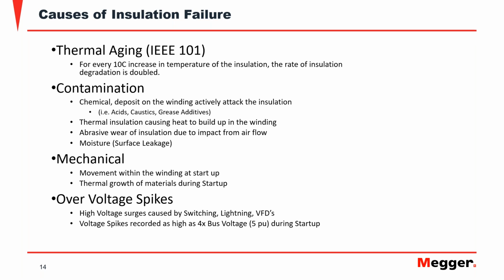If we have the motor connected, as is the case today for, I would say, more than 50%, a great deal of motors out there are connected to variable frequency drives, which operate on the principle of switching millions of times per cycle in order to build the waveforms and control the motor. Well, that switching damages the insulation, and that switching can also be caused by the operation of other motors that are connected to the same line, electrical noise, lightning, etc.